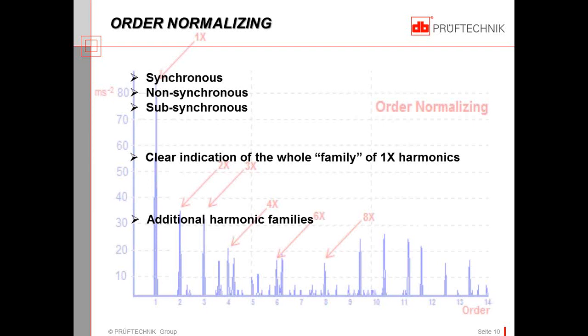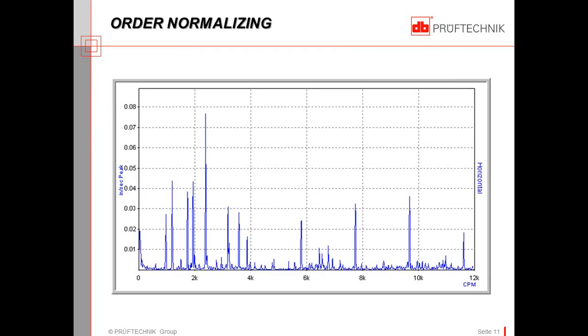So let's have a look at a typical spectrum. If I asked any of you to tell me what you think about the spectrum, first of all, you might look at the Y scaling and say, well, this is a no-brainer. It's a small amplitude anyway, so we've got bigger fish to fry. But for the exercise, we'd have very little to say about this spectrum without any sort of information about the fundamental. Now, most often the analyst has an idea of where that fundamental is, and the process of order normalizing this spectrum would proceed as follows.